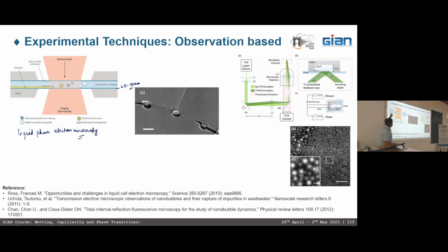We have the same membrane on the top side, and these 2 membranes are spaced using a spacer. Its height will depend on how thick a channel we want. Let's suppose that this spacer is 150 nanometers. It means that the liquid thickness in this channel would be around 150 nanometers.